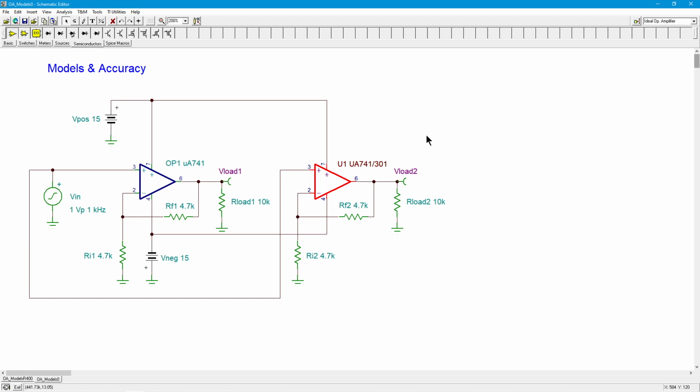And remember, a SPICE macro model is just a human readable text file, so you can load it into something like Notepad and read what it says. Usually in the comments, it'll indicate what it does and does not model. So it wouldn't be odd to grab an op-amp model that says it does not model distortion or does not model noise. That's good. They tell you what the limitations are. Anyway, getting back to where we were.